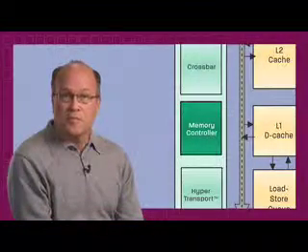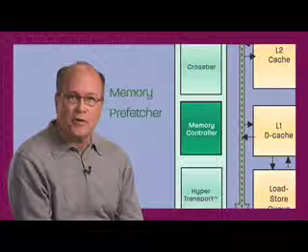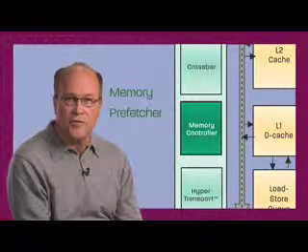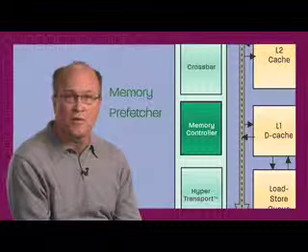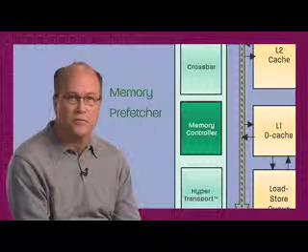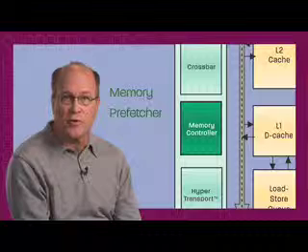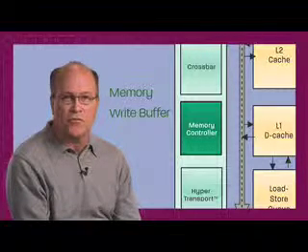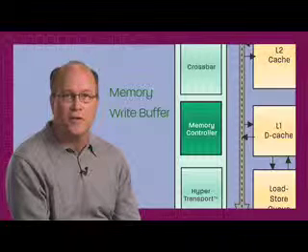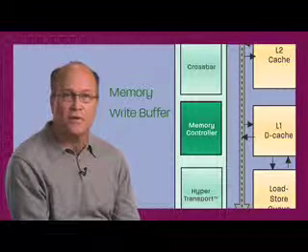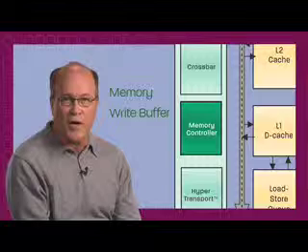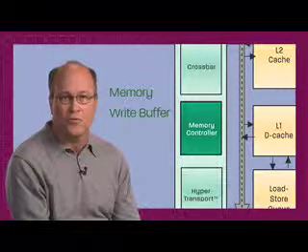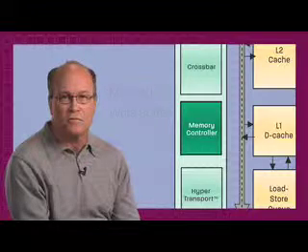A new feature of the memory controller is a memory prefetcher added close to the memory. It speculatively opens RAM pages and is intended to improve the delivered bandwidth inside the processor. We've also added a memory write buffer. We think this is significant because the time cost of switching from read to write mode in current RAM protocols is steep. The internal memory write buffer permits all writes to be accumulated so you won't have as many direction switches in the RAM protocol.